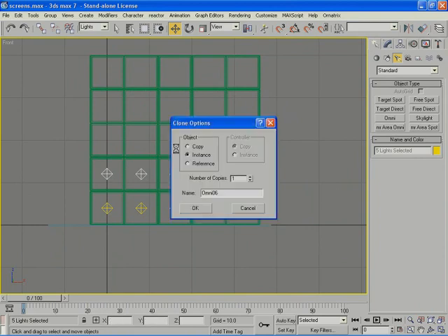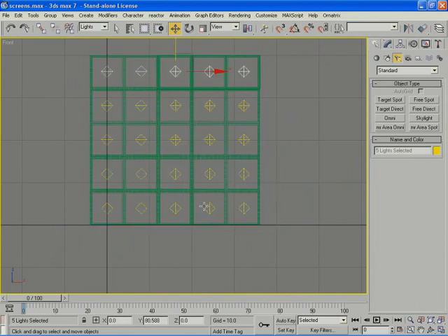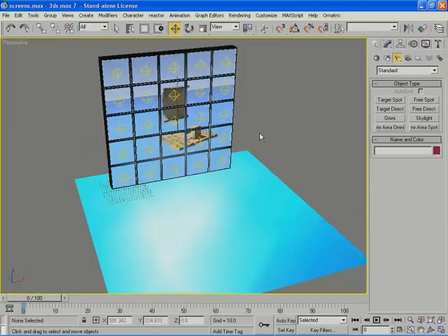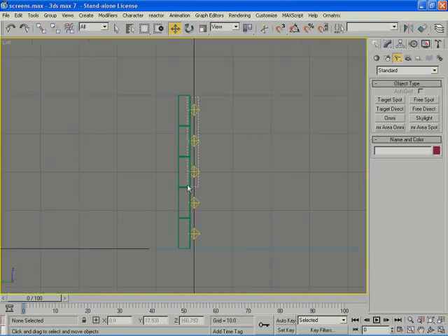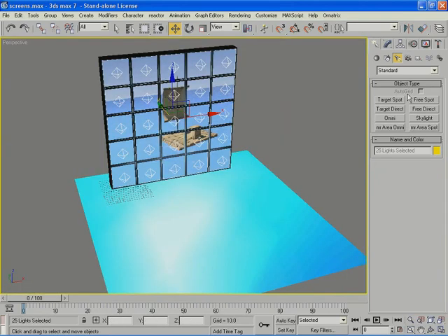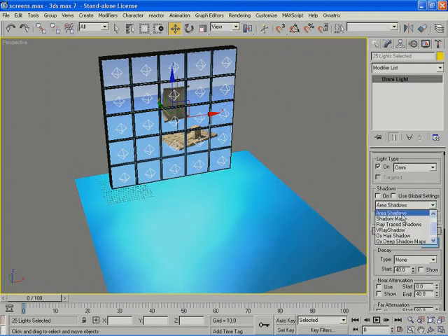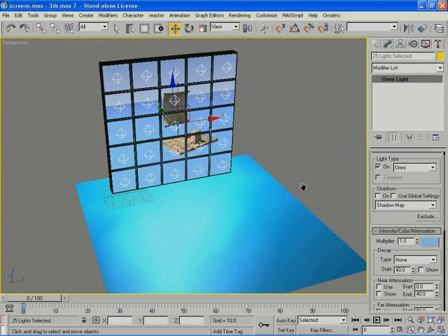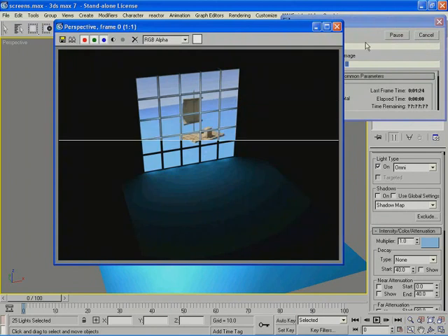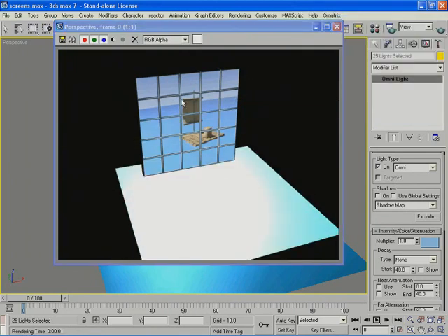Okay, so now the trick is that, first of all, the lights should go inside the screens, because if they don't go inside, I'm going to have a shine around the lights. So this is the default here. I'm going to regain my default. If I just render this way, it's going to look very bad, really, because the plastic is being lit by the lights. And normally the plastic will not be lit by the lights because the light is protruding outwards and the plastic will not be that lit. So this is the wrong way, really.